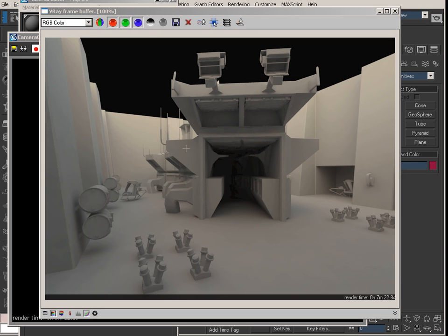All right, so now that we've done that, we're actually able to get some very rich lighting in this area and really get some depth into these colors. But one thing to keep in mind, that you're probably never going to be able to get a really sharp shadow out of an HDRI. So if you were going to do it, and we're going to cover this later, when you're going to use HDRIs or do image-based lighting, it is generally best to supplement it with direct lighting. And that's the only way to really do it, is to have some direct lighting that is being used, and use the HDRI as your fill light. But the fill light sort of becomes a critical point to your whole renders.